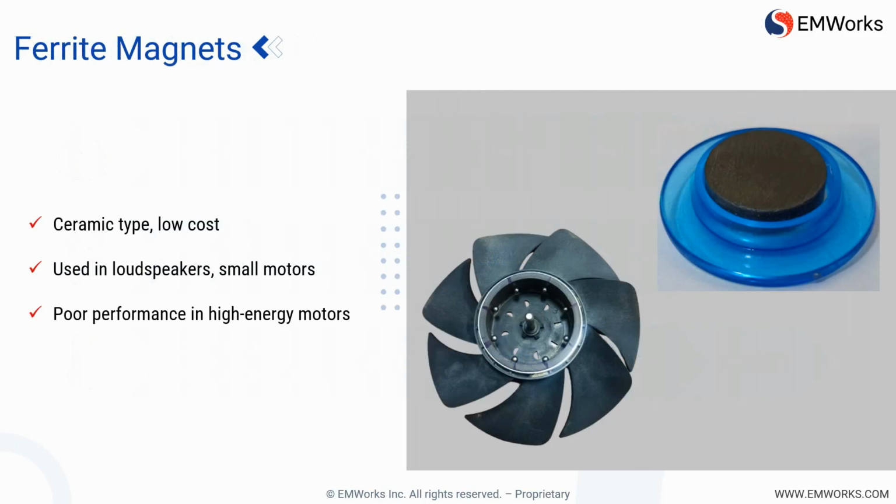Ferrite magnets, often referred to as ceramic magnets, are composed of iron oxide blended with strontium or barium carbonate. They belong to the class of hard ferrites and are known for their high electrical resistivity, which helps reduce eddy current losses in AC applications.